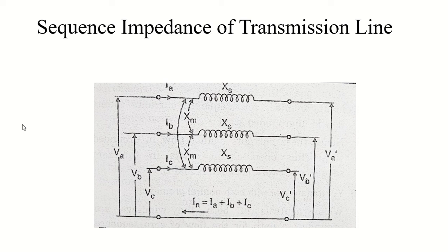These ground wires are grounded at several towers. If you have seen the towers, you will see that the ground wires are grounded at several towers, so the return current in the ground wires will not be uniform. It can be uniform, but it will not necessarily be uniform all the time for the entire length of the line.